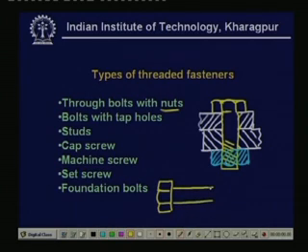It's a cylindrical body and there are threaded parts over here. You see there is a sharp change, and that is not allowed normally in any machine component because of stress concentrations. So, we have a radius. This is the fillet radius; normally a radius is given.